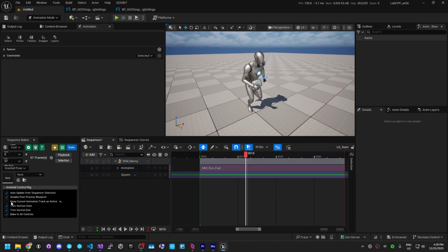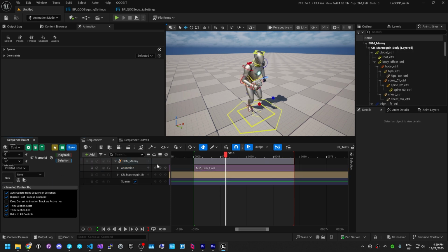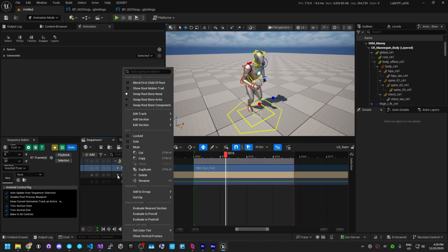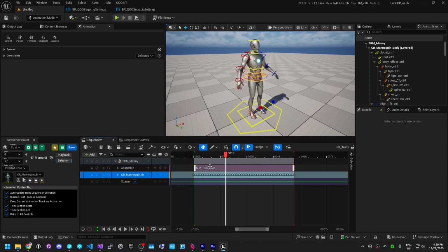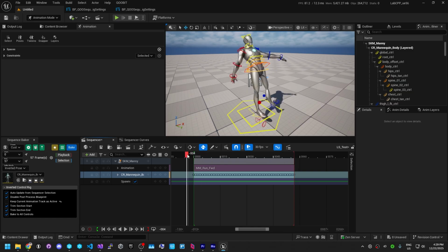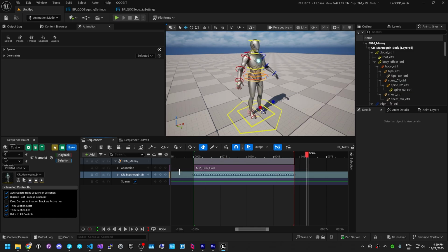All right. And similarly to the other bake sections, if we did this manually, you'll see that we have a bake that is happening to the unbounded range for negative infinity and positive infinity. So we're going to do this bake again here, inverted pose. And you'll see that although the keys are within the frame range here, we have negative infinity and positive infinity for the handles here.